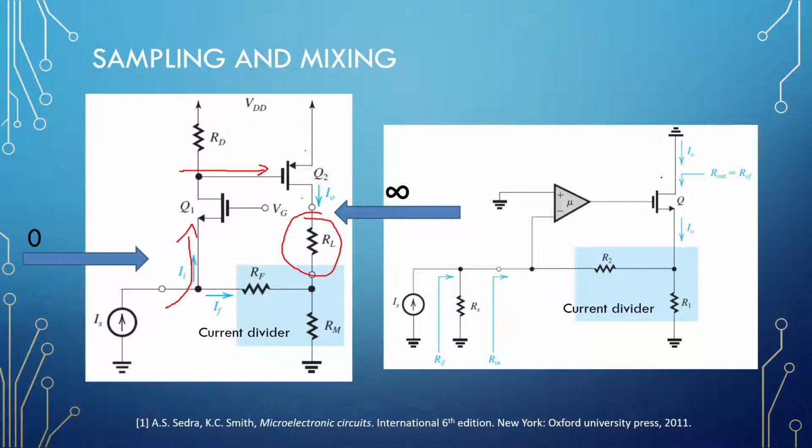The trick that I spoke about that we're going to have to use on this amplifier will not be valid in this one on this side, since we are using a PMOS. It is better to use PMOSs if you want your mathematics to be a bit easier, but using the NMOS will have a definite increase in output impedance, and the load should actually be sitting up here for this problem, and this ground is just a small signal representation.